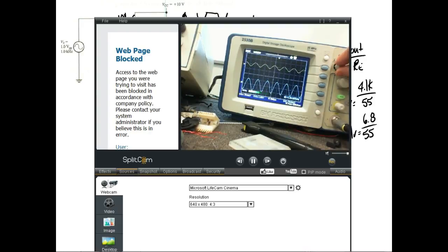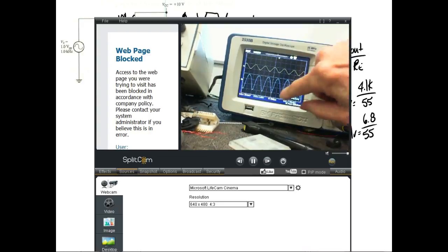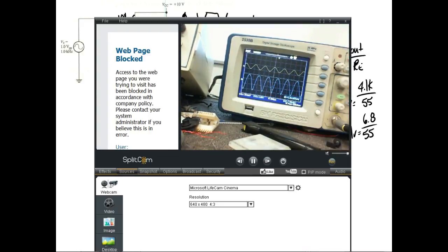Okay, so roughly we're putting 5 millivolts per division, 50 millivolts per division. We're putting a little less than 50 millivolts in. So I'm putting 50 millivolts in. And it's already starting to clip some, and I'm getting 1, 2, 3 volts out. And I'm going to come up here now and open up the load. And what did the gain do? The gain went way up, right? Understand that? Are we okay?